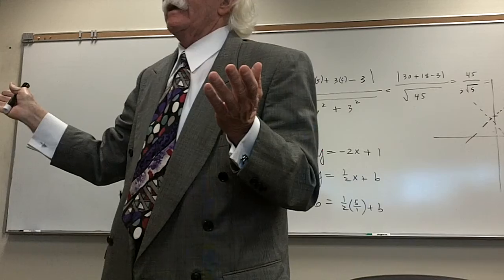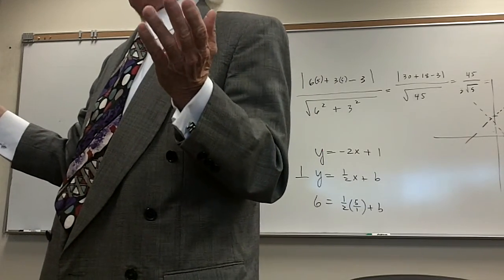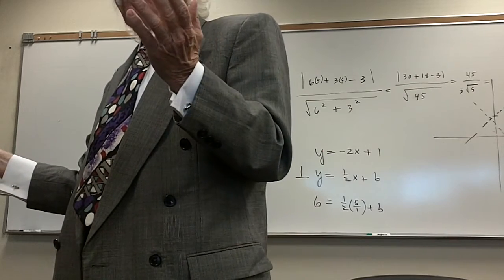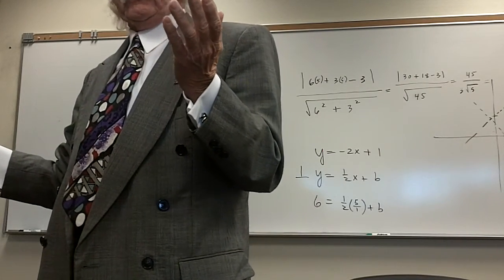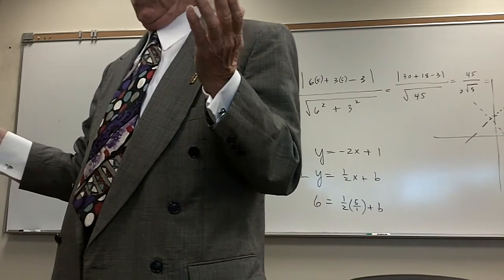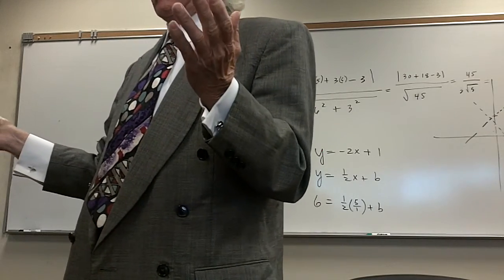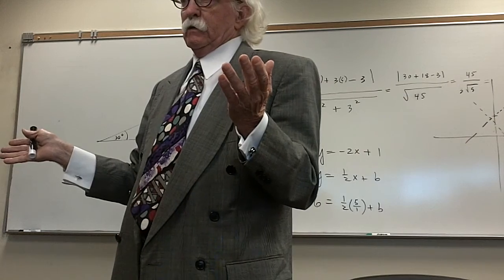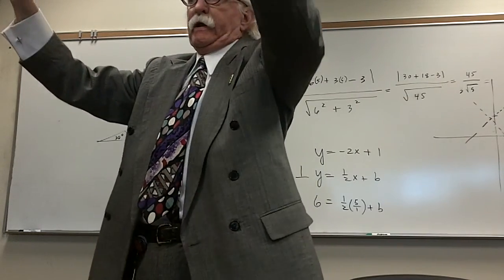So guess what? When mu is greater than the tangent of the angle, it's going to stay up there. When mu is less than the tangent of the angle, it's coming down, unless you push it up there and hold it up there.